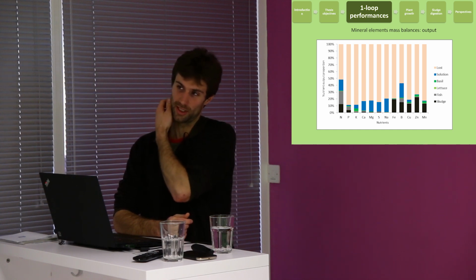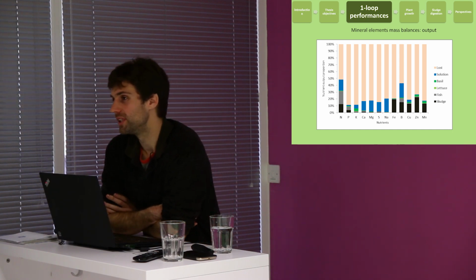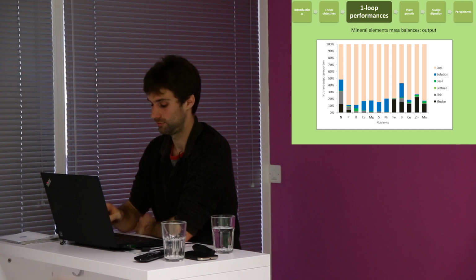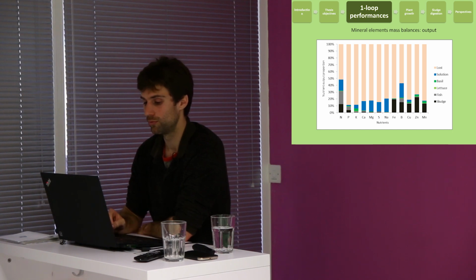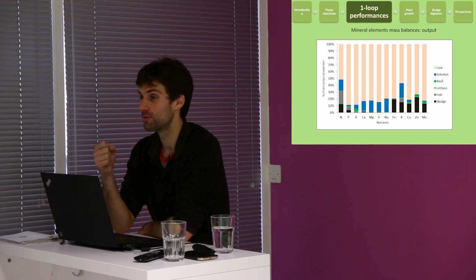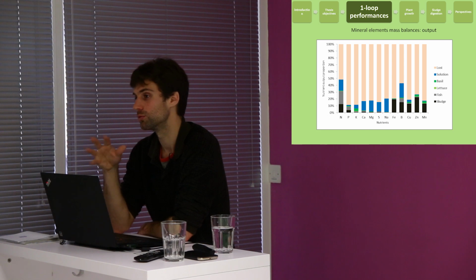Your 3% is water that you send to the drainage. It's not evaporation. It's both. The evaporation we can estimate, and it will be less than 1%. And why do you need to send water to the drainage? We did it for cleaning the filters and when we remove the sludge. And sometimes we removed some water to control the pH. So we just threw water out at some point.